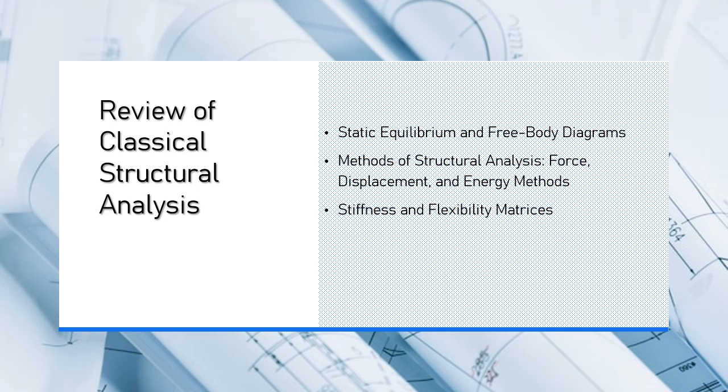2.4. Comparison of methods. Method. Type of structures. Advantages. Disadvantages. Force methods. Statically indeterminate beams, frames, trusses. Direct solution of internal forces. Requires careful selection of redundant forces and solving compatibility equations.